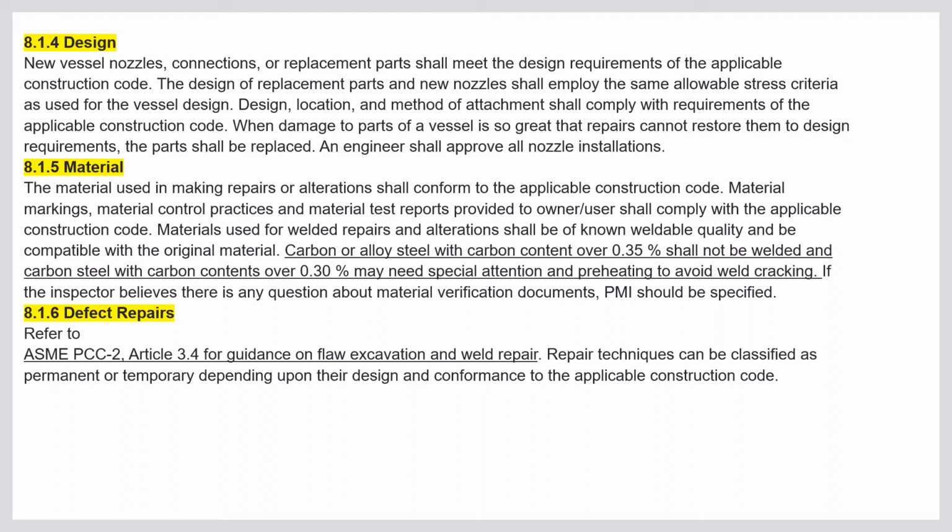So design. New vessel design, connections and replacement parts shall be made to the design requirements of the applicable construction codes. This is important. Always this happens according to the applicable construction code. The design of replacement parts and new nozzles shall employ the same allowable stress criteria as used by the vessel design.